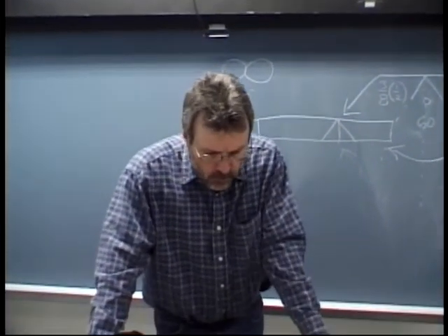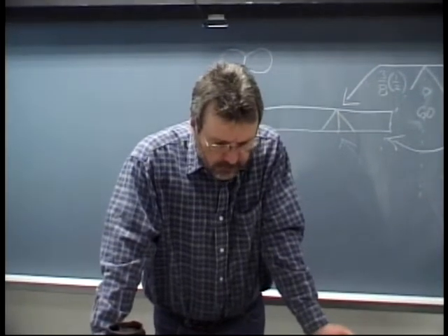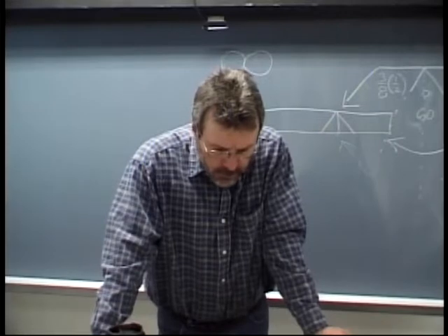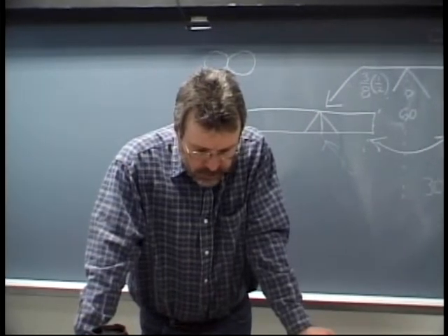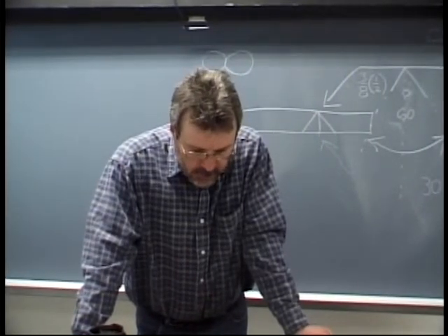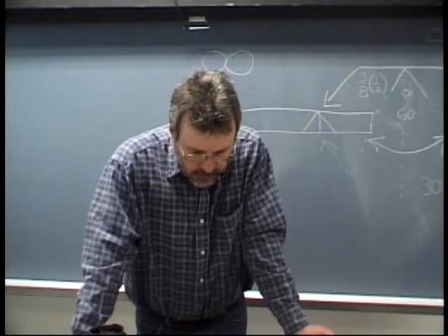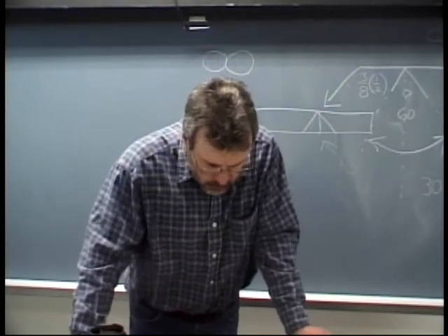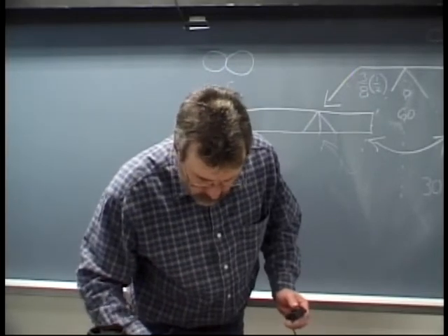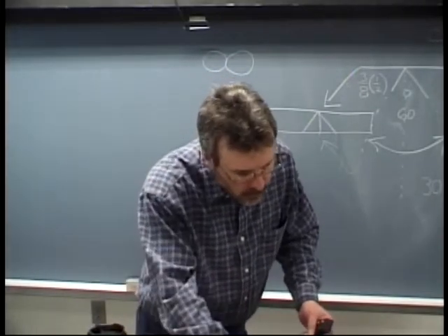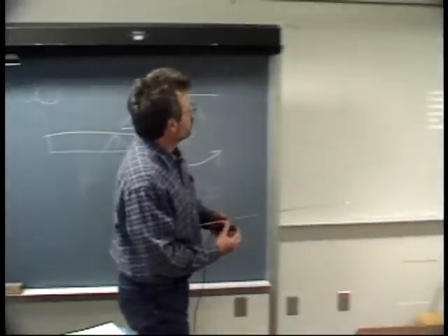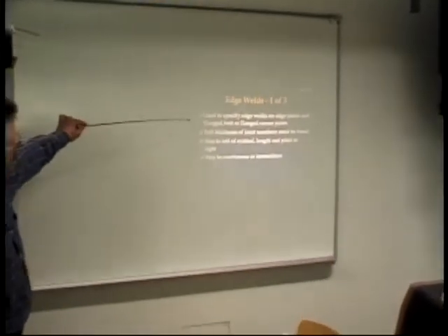The edge weld is a weld that totally consumes the full thickness of the edge of the joint it is being applied to. It is typically used on edge joints, flanged butt joints, or flanged corner joints. And it says figure 30-12 represents some various examples of edge welds. My slide here says basically the same thing.